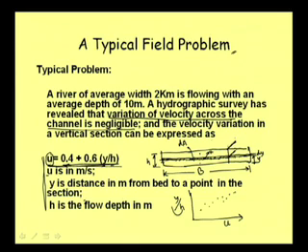And as I have explained, at the surface, when your y is equal to h, your velocity becomes equal to 1. You put y equal to h, you are getting 1. And at the bed, when your y equals 0, you put y equal to 0, you are getting u equal to 0.4. So, your velocity is 0.4 here, and you are getting 1 velocity here. Suppose this mass is 1.